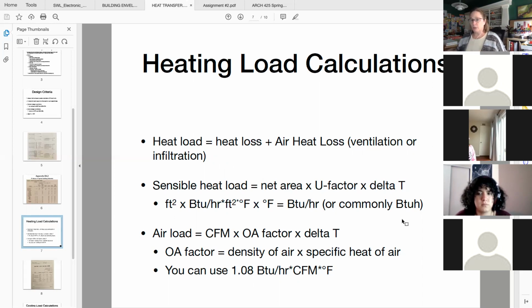So in heating load conditions, you do not have to take into consideration the solar orientation, because you know that the outside is already cooler and that any solar gain that's hitting that surface is not going to try and migrate into the space because it's cooler on the outside. So if heat hits a brick wall and even what's absorbed, that conductance is still going to go back to the exterior and not to the interior. So in this condition, solar orientation is not important. The inverse is that when we talk about cooling, solar orientation is a big factor of calculating a load because you have that added, not just temperature differential, but that added solar radiation that's hitting your wall assemblies or your roof assembly.